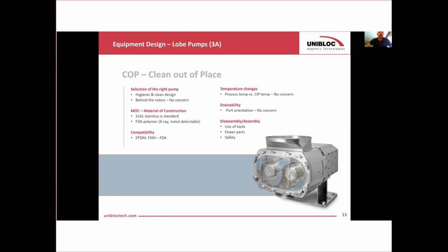The material construction, 316L, is still going to be your industry standard. However, you do open up for alternative materials, such as an FDA polymer that can be either X-ray or metal detectable, depending a little bit on what you have for a detection system downstream.